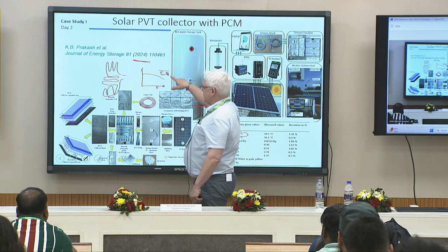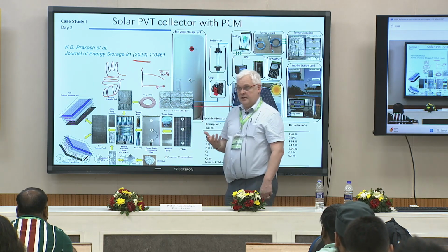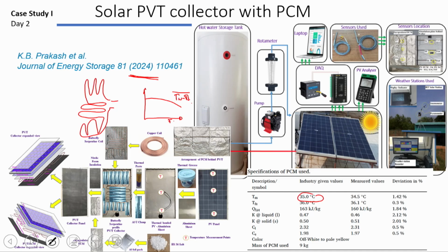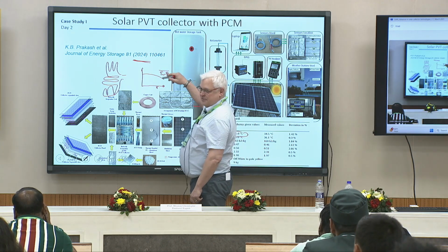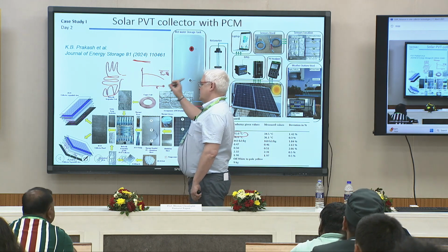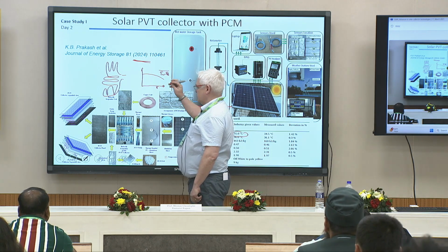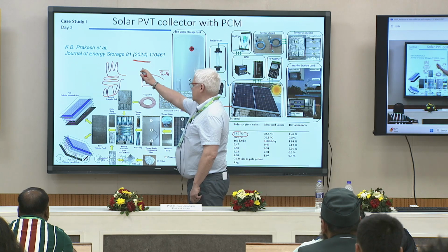The temperature of water minus the ambient temperature becomes big as a ratio when the water is close to the ambient. But we have no use of water at the ambient temperature. Of course, a flat plate uncovered has a good efficiency when the water temperature is near the ambient temperature, compared to the other that will be like this.